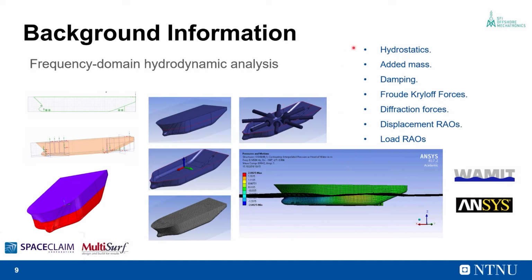The output of such analysis is the frequency dependent added mass, the frequency dependent damping, frequency dependent Froude-Krylov forces, frequency dependent diffraction forces, the displacement response amplitude operators, and the load response amplitude operators. The displacement RAOs give the response of a body in relation to a wave of unit amplitude, while the load RAOs give the load acting on the submerged surface of the body associated with a wave of unit amplitude of a particular frequency.